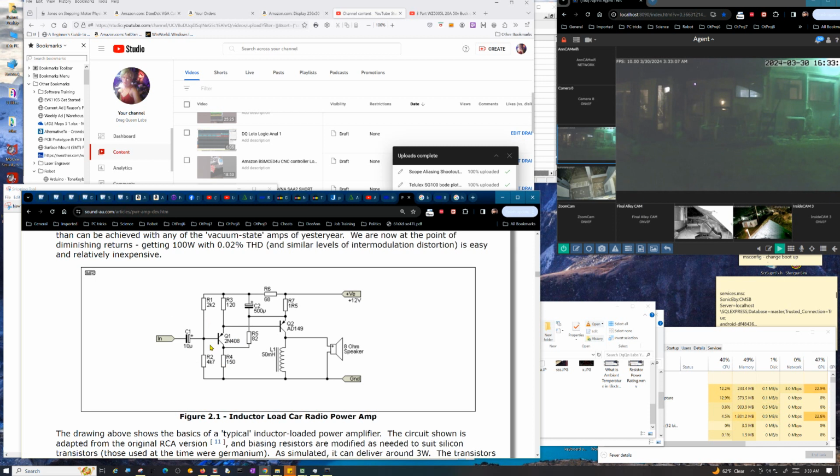Well, it's not, but you've got to really take into account what the voltage on this side of the capacitor is going to be versus this side. And something that's an unspecified input should always actually come with a voltage warning on it, you would think. Okay, input, but only input, make sure it's well below 8 volts. Because even the signal, that's what I'm saying, if it was 8 volts input and 8 volts output, okay, there's 0 volts across the thing, and then you apply a signal at that point, then it's acting like AC, okay?